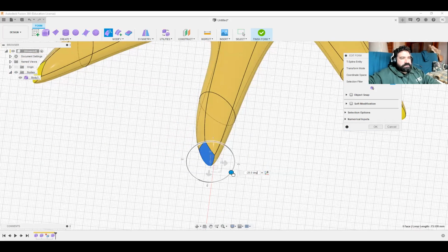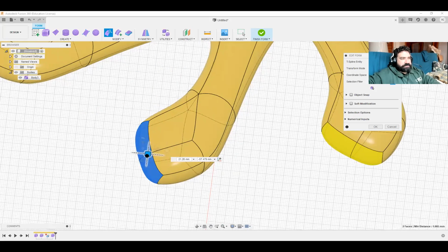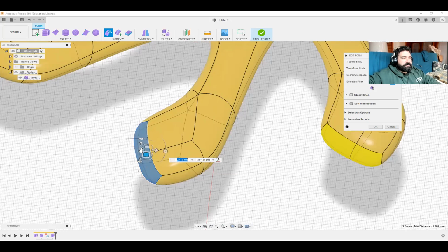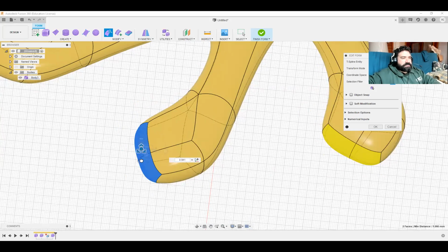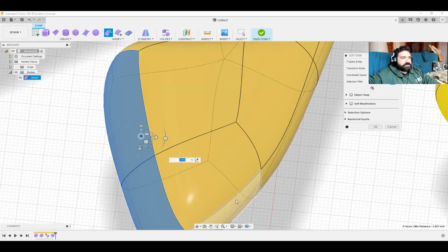Rotate that a little bit. Now let's select multiple areas and we'll drag that outward with an Alt extrusion again. Oops. I'll warn you, a lot of times it does get difficult to select what you're actually wanting to, out of this gimbal.